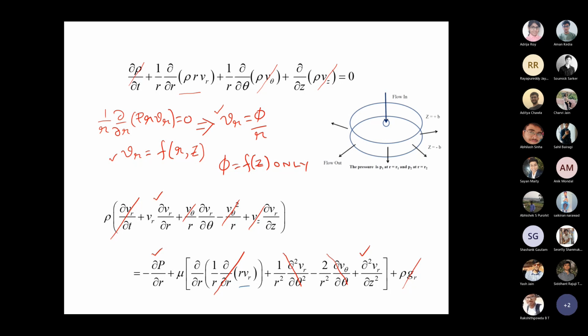Now, many of you are aware that the fluid mechanics that we deal with has found new usage in situations where the system size is small, where the gap is small, where you are having flow through a microchannel or flow through conduits which are extremely small in size. So the pressure gradient applied could be large in order to initiate flow in such small systems. So therefore the convective part could be neglected since the velocity of the flow is small.